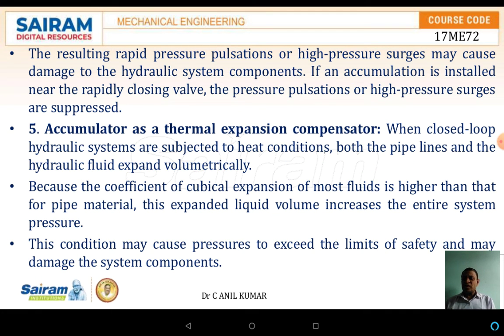Another application is that accumulators are also used as a thermal expansion compensator. When closed loop hydraulic systems are subjected to heat, both the pipelines and the hydraulic fluids expand in volume. Because the coefficient of expansion of the fluids is higher than that of the pipe material, the volume expands.